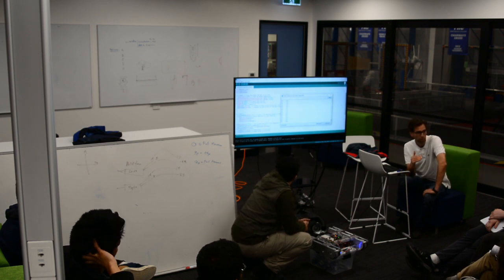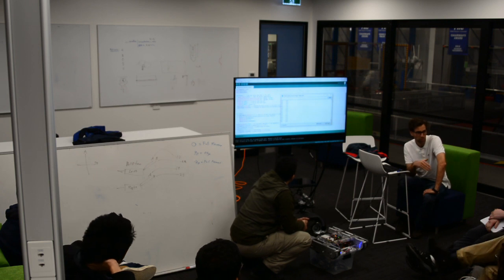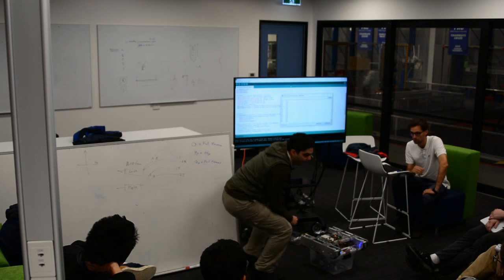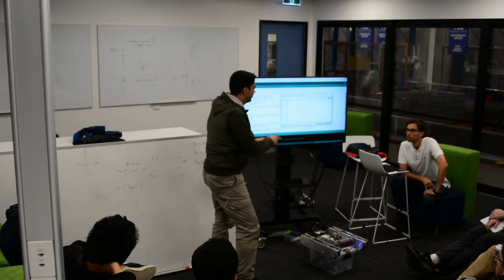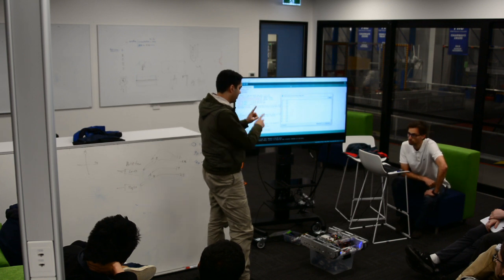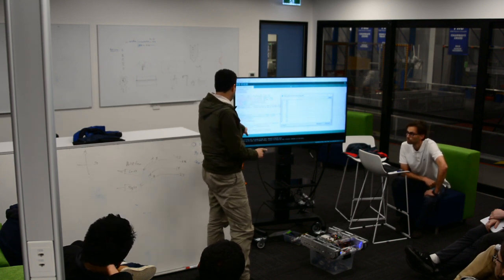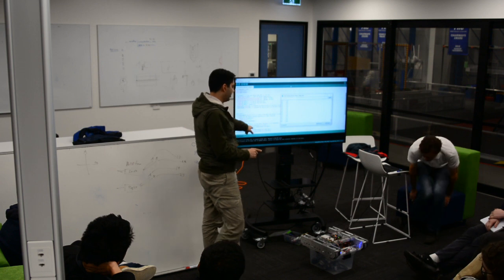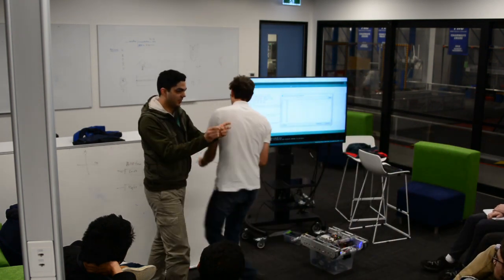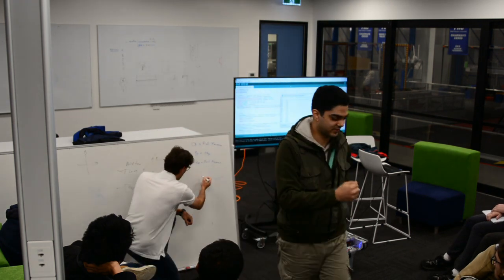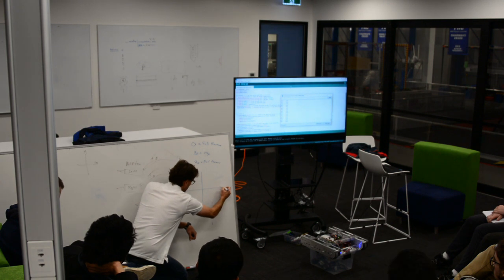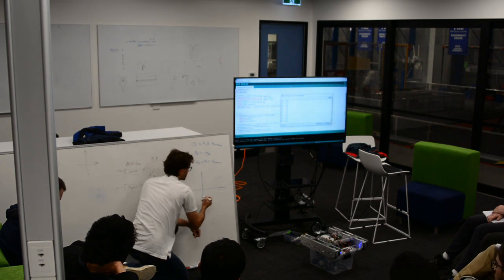For speed control, well, there's other things you can do. I mean, the problem with speed control is you need to maintain some throttle to maintain speed. So you can't shut your throttle off necessarily. If you do, it's just not as good. Okay, so where do we go next from this? Any thoughts? You take the difference. You want to create a P controller. Let's do a P controller. Take the difference of target position and count, and then you use that as your... Yeah. So what we've just done is, this is the way I like to think of this. You've got...